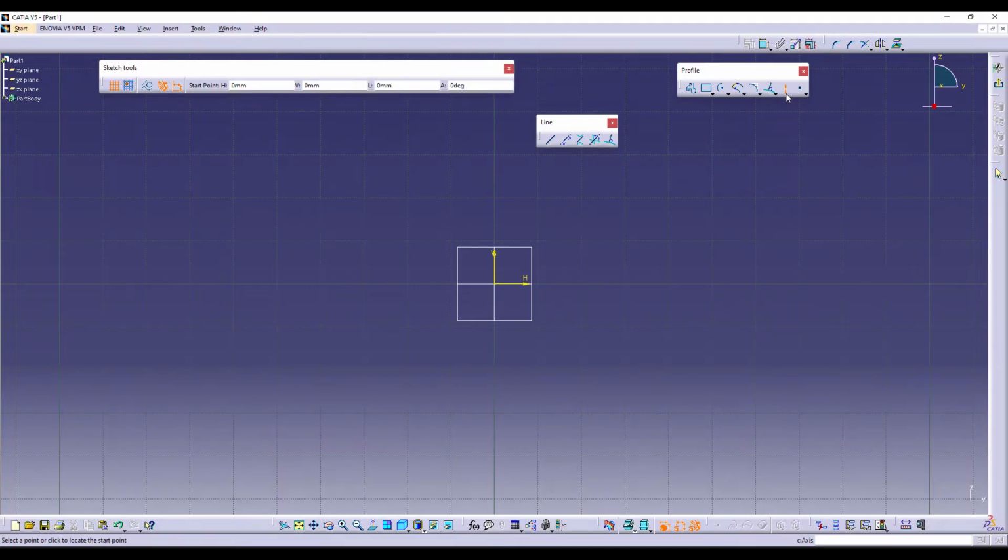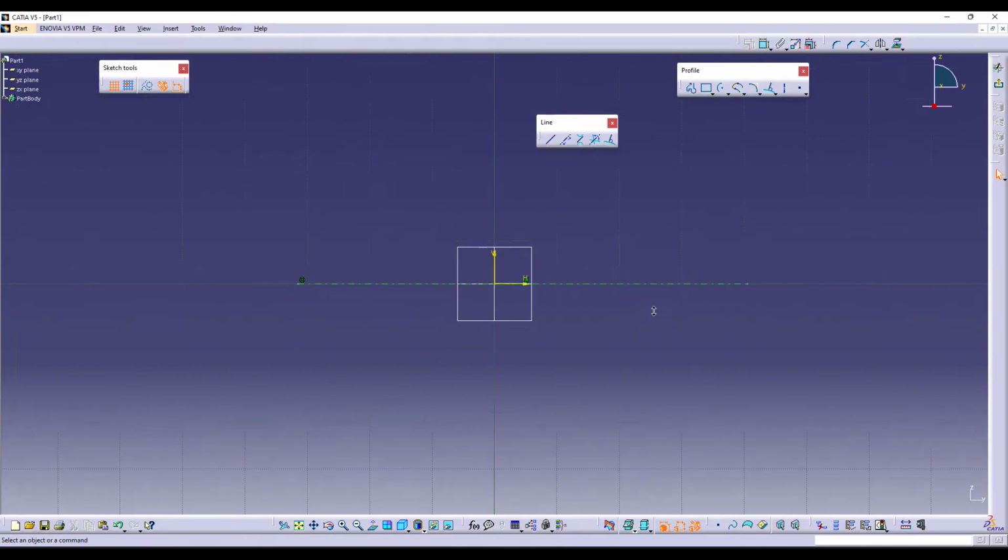So if I create an axis, you can use left click, give the start point of an axis and the end point of an axis. Even the notation of the axis is dash, dash and small dash. The axis is not infinite because the cylinder or any spherical components has a definite length. We can give to that particular length only.